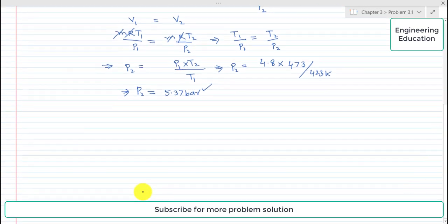So now, second, we have to find the Q, heat supplied during the process. It is a constant volume process, so for that we have the expression Q is equal to mCV (T2 minus T1). We know all these values, so putting the values directly, m is 1, the value of CV for air is 0.718 kilojoule per kilogram per Kelvin,